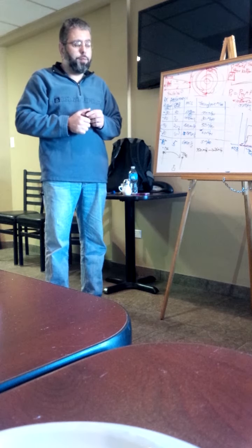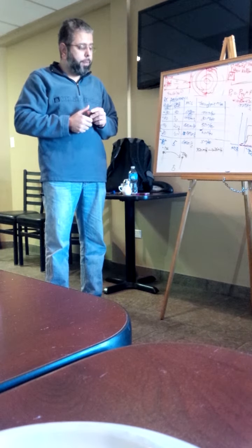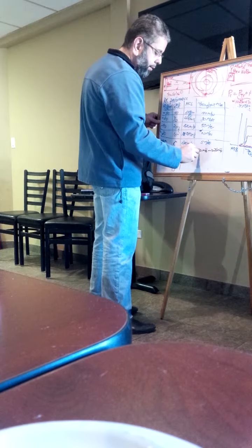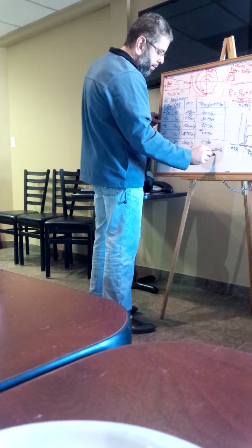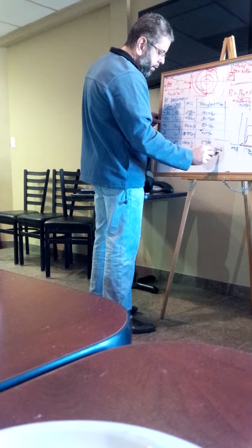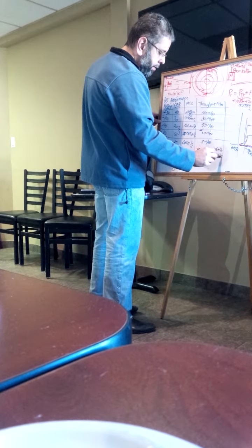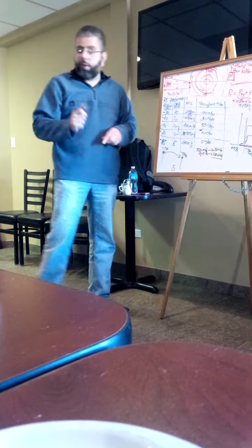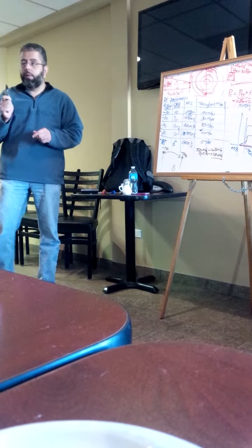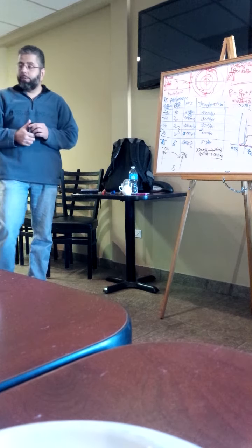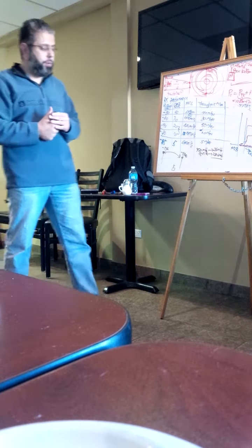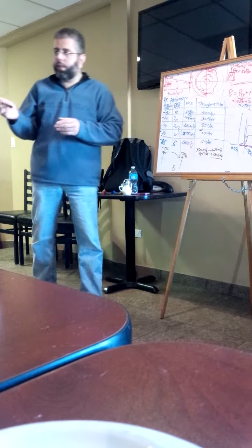So it'll give you 0.25 megahertz, which is 250 kilohertz, right? So if you have 83 channels, each channel can be 250 kilohertz wide. Probably good enough to support voice in most cases, in all cases really, if you wanted to do voice, but they're just sending some data.